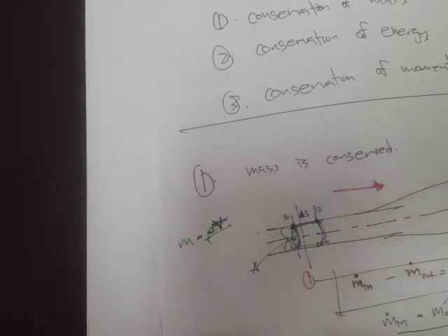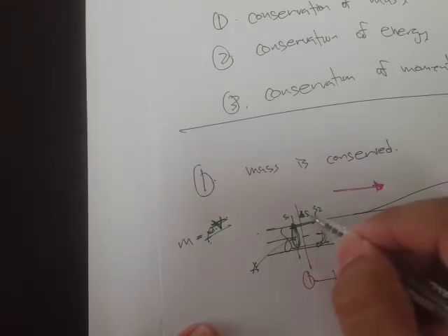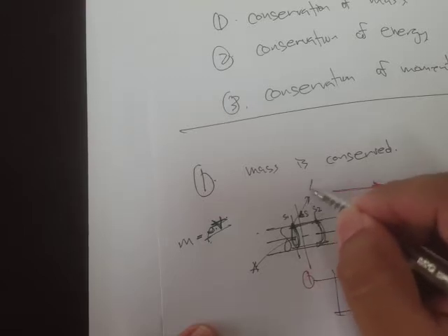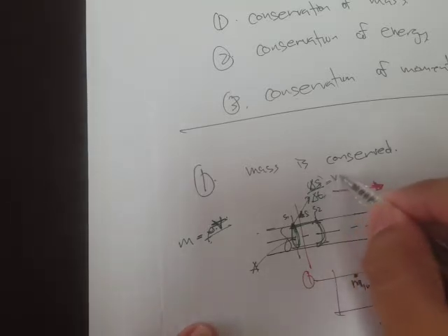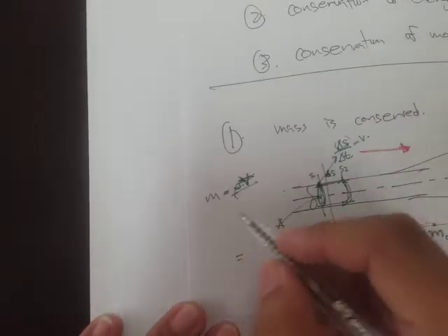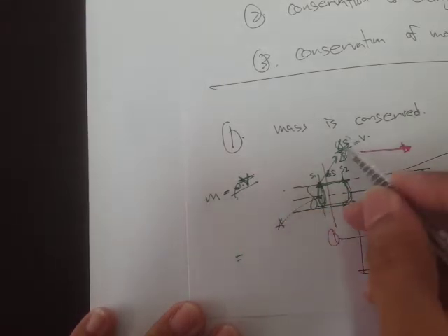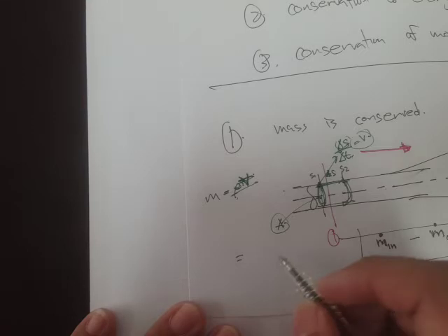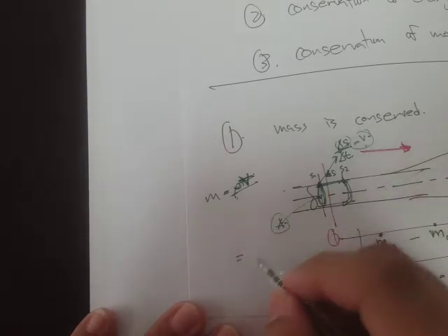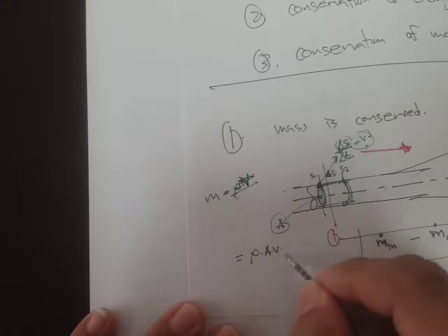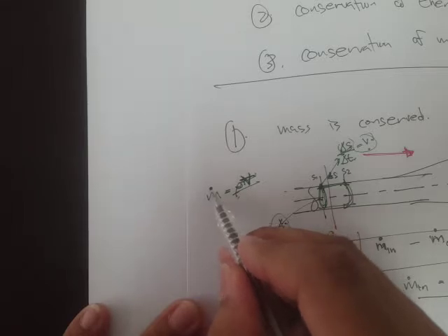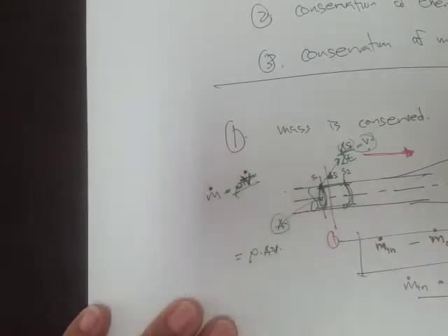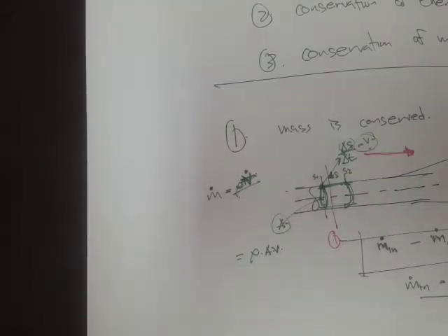Now since we are referring to the rate of change of position, that's going to translate to delta S over delta T. So displacement divided by time, that's just velocity. Therefore, if we substitute this velocity here, that's going to be rho A times the velocity, and that's going to be the mass flow rate. So that's m dot, and this one should be m dot as well, because we're talking about fluids in motion.